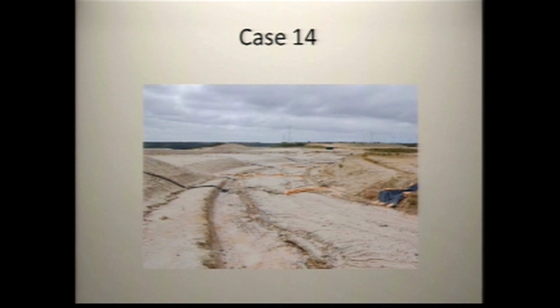Again, this is a pretty steep street, and they need probably twice the gravel bag chevrons to knock the energy out of the water to keep it from rilling in between them. They just don't have enough. So you're getting a lot of turbidity. The turbidity is going to make it all the way through and out to the creek.